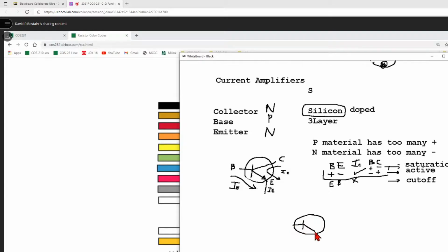I opened up a circuit. And I measured the voltage right here and right here. And relative to the 0 volts I saw here, I saw 0.7 volts here. Then I came over here and I measured between the base and the collector. And what I measured here, between this and this, is basically 0 volts. So the base is higher than the collector, and the base is higher than the emitter. Higher and higher, we would know the transistor is operating in saturation.